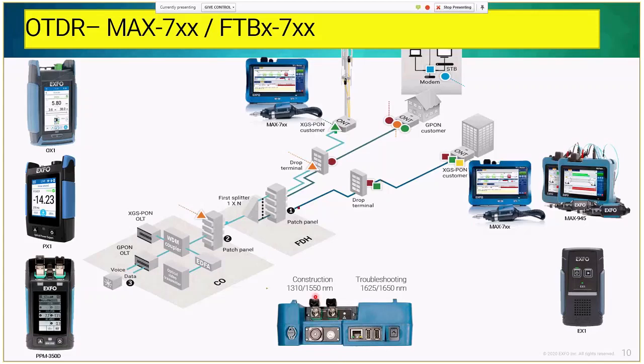Here, just to mention, there are two different ports normally seen on the OTDR, and for whoever is in the field, there is always a difference between them. One is mainly used for construction, which will be 1310, 1550. You always need two ports or two wavelengths for detecting elements like macrobends. As good practice, you can use the three. So you can use 1310, 1550, and one of these ports, and then you will do your installation tests, commissioning tests, in a three-band way. And our device will be able to combine them and give you one SOR trace.